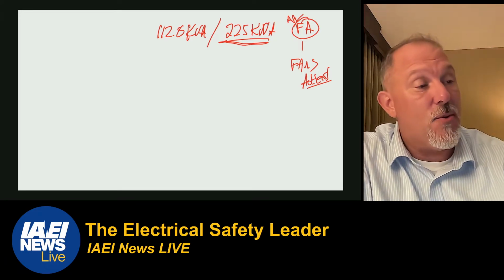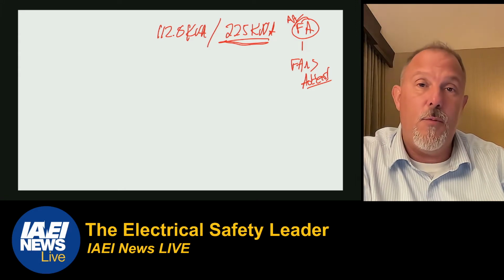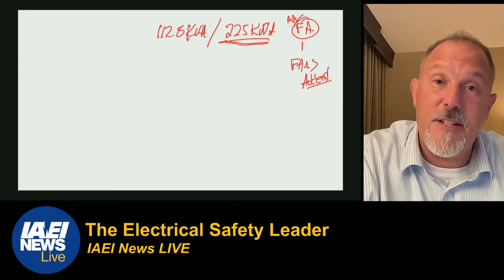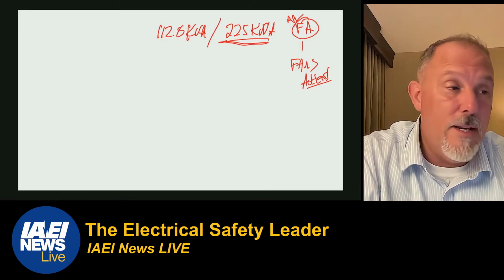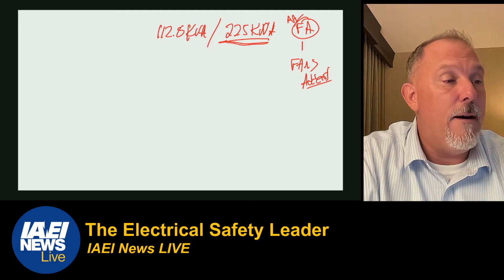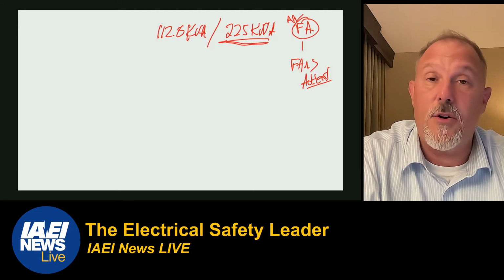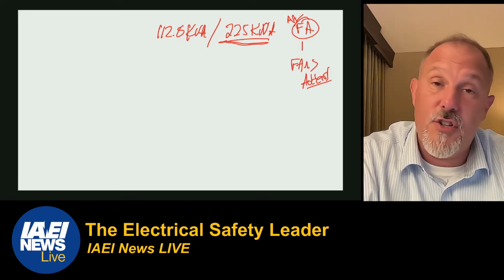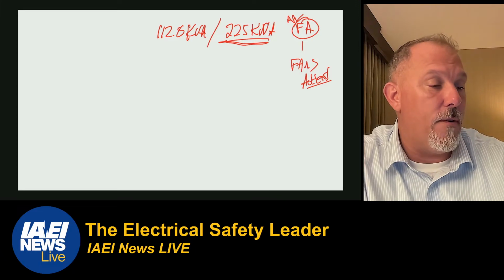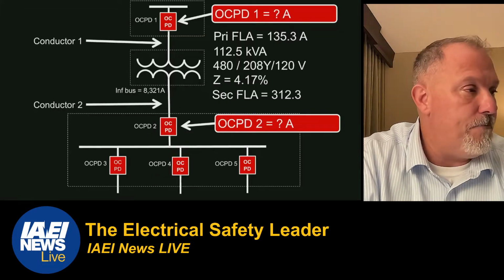And I have to make sure that when I'm running off of whichever full load amps of that transformer, that I'm picking my overcurrent protective devices correctly based upon whether I have fans or not fans, and what parameters are impacted. Are the inrush currents impacted? Is the impedance of the transformer impacted? So those are other important aspects that you need to think about.